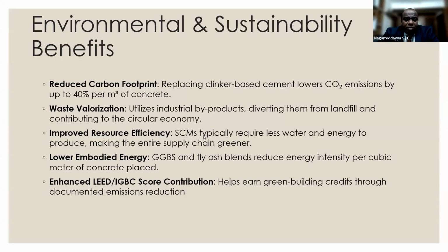SCMs, supplementary cementitious materials, typically require less water and energy to produce, making the entire supply chain greener. Lower embodied energy: GGBS and fly ash blends reduce energy intensity per cubic meter of concrete placed. Enhanced LEED or IGBC score contribution: replacing OPC with SCMs, GGBS and fly ash, helps in green building credits.